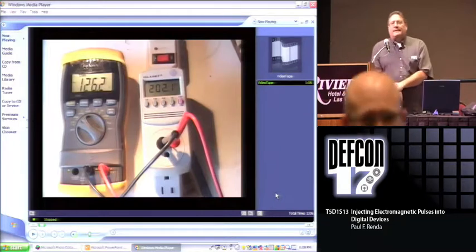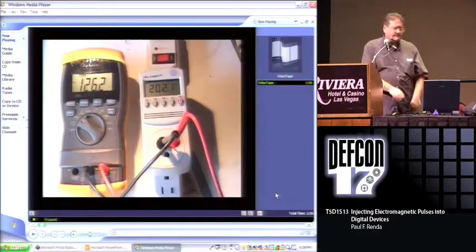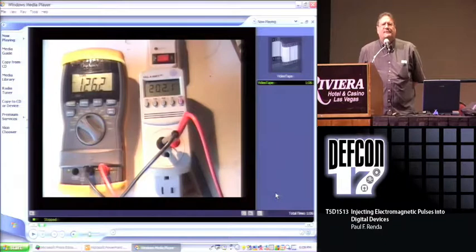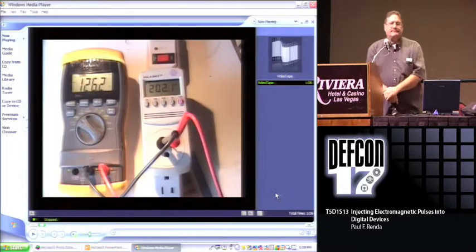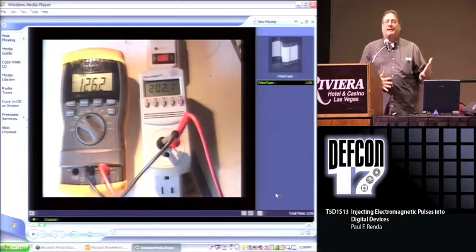No, I haven't. Interestingly enough, the cable box, I demonstrated the cable box, right? Did I? Oh, I did. The cable box is almost all metal. I also tested some other things where the box was all metal, and I would think that it acts as a Faraday cage. I was able to pulse it and bring it down. The only thought I can have is I must have injected enough of an energized charge into the external shell that it re-radiated the charge internally and externally, and it brought the CPU down. So in other words, Faraday shields may have been tested in such a limited way that if somebody's trying to create destructive pulses and does a wide range of experiments, they may find that these Faraday shields do not hold. I hope that answers the question.